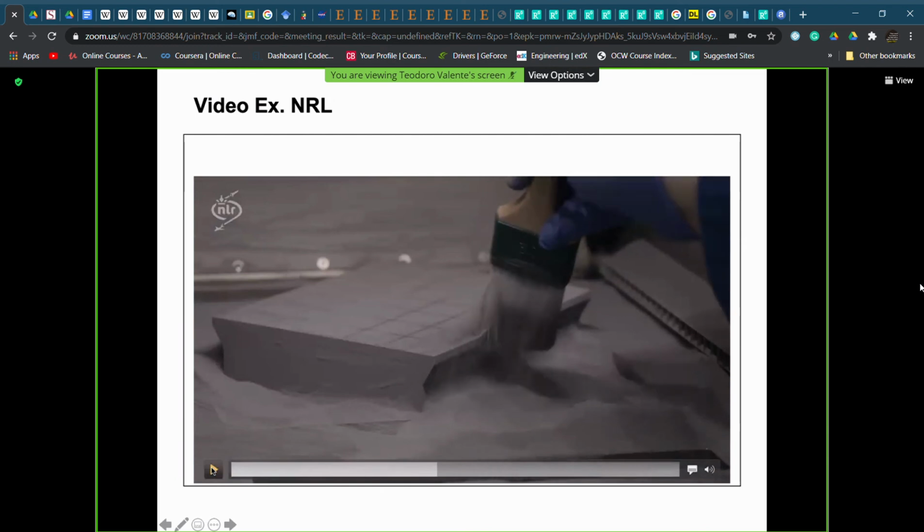You see here? That's the bed of powders from which the final component has been fabricated by using, in this case specifically, a laser head, and the remaining powders can be used, recycled, and reused for the fabrication of other components. For this, somebody says that this technology is also a sort of sustainable technology because it reduces the scraps, and the meaning is related to the main technical features of the additive.